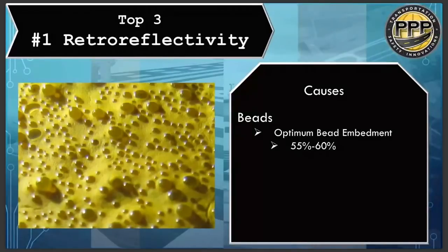We find this when our pigment or our paint or our coating is not thick enough to let that bead drop into the material. So these larger beads will do kind of what Mike was talking about: they'll peel out before long. They'll have an early release, and that's the difference between a small bead and a large bead.